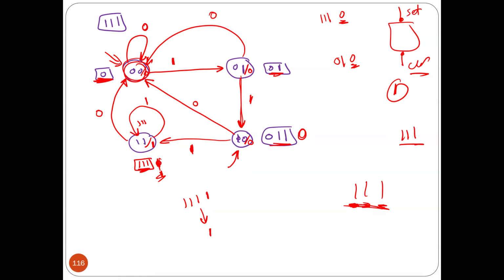Yes. I was talking about the inputs. You started as 0 and then 0, 1, and then 0, 1, 1, and 0, 1, 1, 1, and then it would continue as many ones as you added. But did you start with 1 as the first input? Yeah, you can. But again, we agree in the very beginning I'm going to clear the flip-flops. That means I'm here in the very beginning. Is that okay? And then after that, if in the very beginning I receive 1, not 0, I will move directly from here to here. And then I will start counting the sequence. That will be correct. You got it?